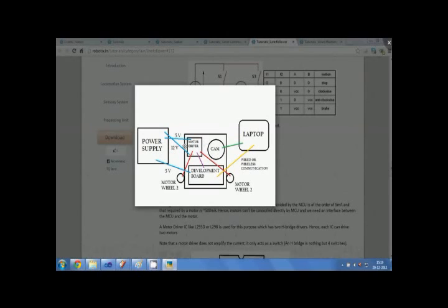If you look at the circuit, 12 volt is needed for the motors, and will again give 5 volt to the development board, which is needed for the running of the microcontroller. Now the development board will be connected again to the motor driver. You may see our tutorials for the standard connections, because the inputs to the motor driver will be sent from the development board.